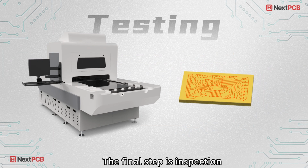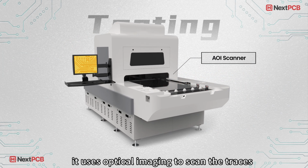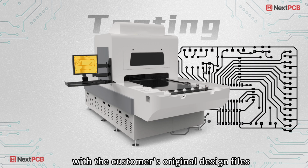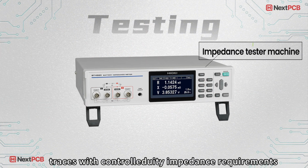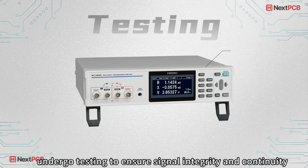The final step is inspection. The circuit board will go through an AOI scanner. It uses optical imaging to scan the traces, then compares the results with the customer's original design files to check for any breaks or defects. After passing inspection, traces with controlled impedance requirements undergo testing to ensure signal integrity and continuity.